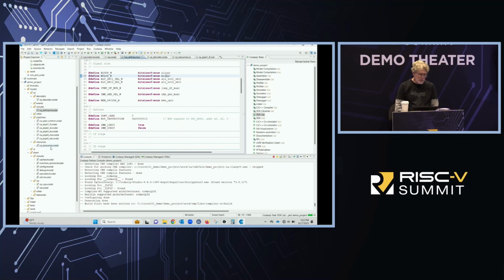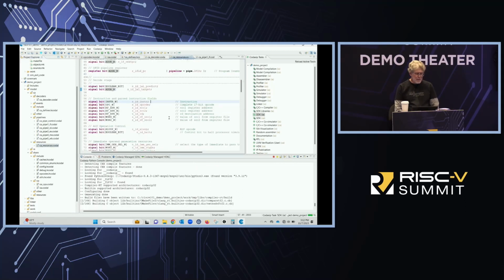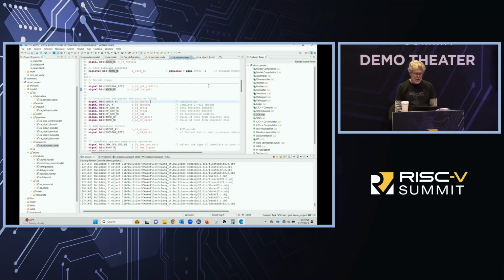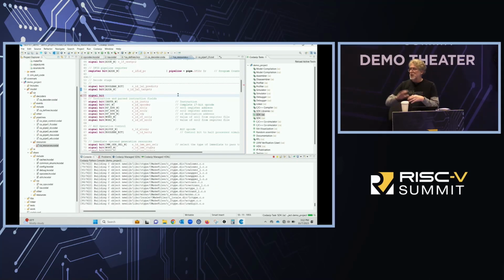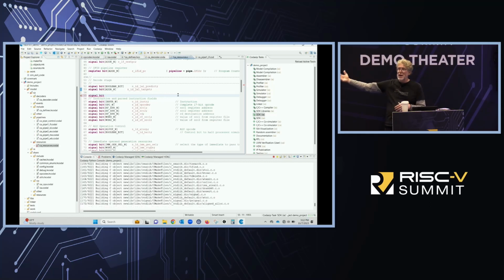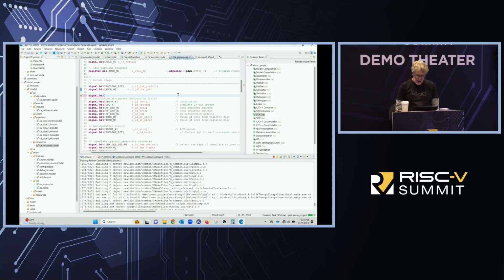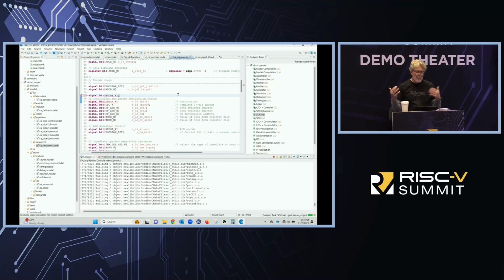Now I'm going to go to my resource, and I needed a few additional resources. So the first one is I need something that when I actually decode multiplier will actually send the microcode to my next stage. So I'm going to say my mul op w. Because I don't know the width of my multiply micro opcode right now, even though I know it's 1, I just don't want to rely on that.